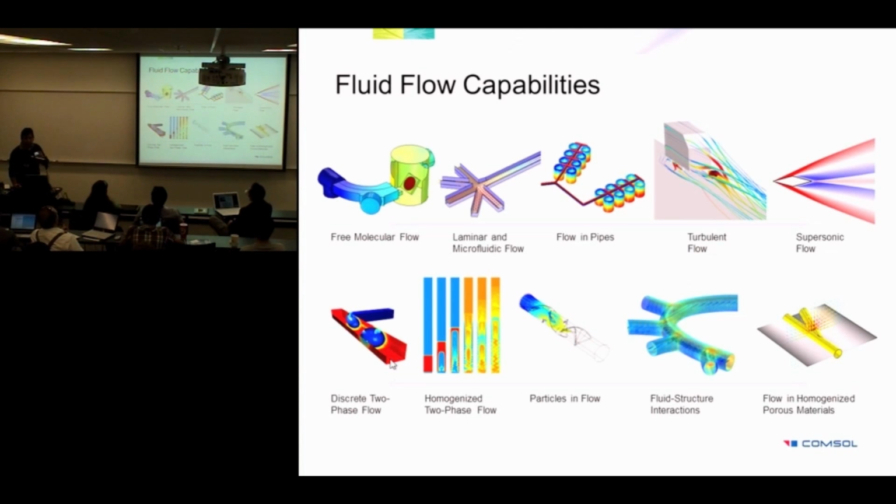And then you have a 2-phase flow phenomena where you could basically capture droplets, oils, and mixtures. So where you are more interested at the interface of that, then you can use discrete 2-phase flow systems. And they can be handled using level set and phase field methods of Comsol, which is available in microfluidics module. And then you can also use moving meshes to capture your interface.